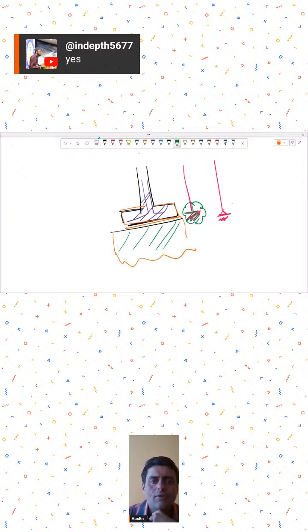Now there is another viewpoint also that, let's say under the effect of wind loads or lateral loads, momentarily there is a rotation that you have allowed. Why rotation? Because you are allowing, let's say, uplift in some portions of your footing under wind loads or lateral earthquake loads, and under some portion of the footing there is a downward bearing pressure. In some portion of the footing you have allowed uplift.